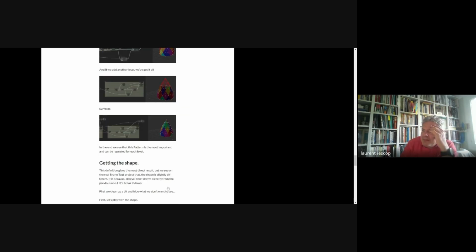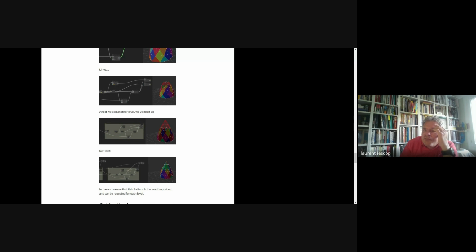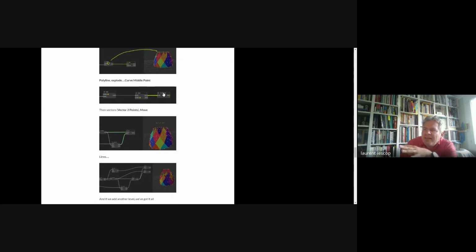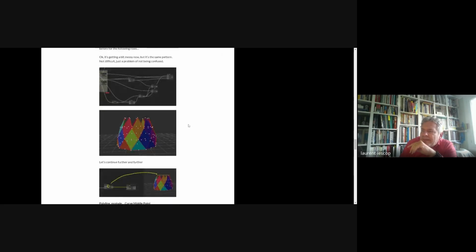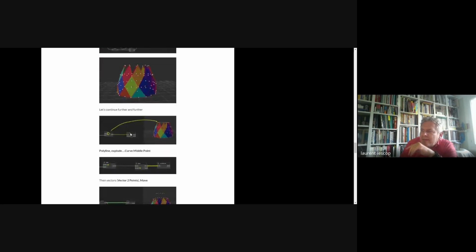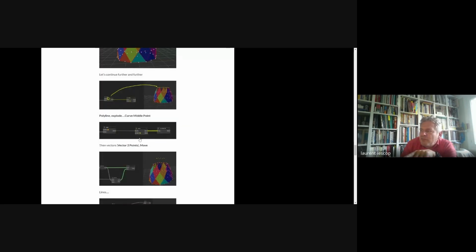When I'm using the four-node surface, I think that the surface from 4 points doesn't accept a non-flat surface. I think it doesn't work in BeeGraphy. If it's not on the same plane, I think you cannot get a surface from 4 nodes.